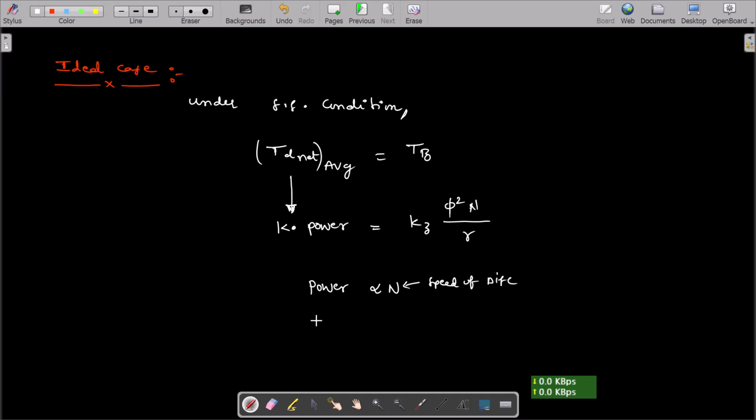This is the power in the circuit or load. The expression for this power will be VL IL cos phi. Already we have seen this expression in the deflecting torque equation.